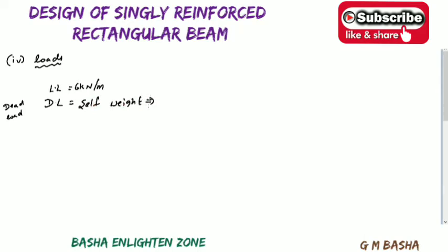For example, my self weight, whatever the weight I am. You take any particular material, its self weight is considered as self weight without moving. For example, my weight will be equal to some 60 kgs. And if I am lifting any books, that comes under the extra load, which is live load, which is moving loads or removable loads. So the live load is different, dead load is different. Dead load means the self weight of that particular member.